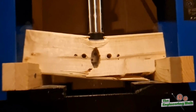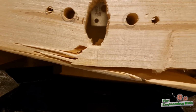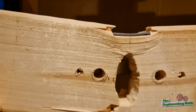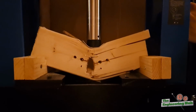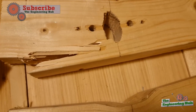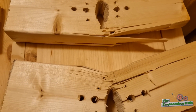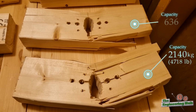This is a 6% increase in capacity compared to the beam without relief holes. I find this result absolutely astonishing and very counterintuitive, but before concluding too much, I repeated the test 2 more times just to make sure that this 6% increase was not just statistical luck. This time, I drilled a few additional smaller holes just to make sure a nice smooth transition in the streamlines is achieved. All of these samples were taken from the same 2x4, so in reality there shouldn't be too much variation between them, but I repeated the test anyway. The new samples achieved 2140 and 2010 kilos, confirming the effect of the relief holes.